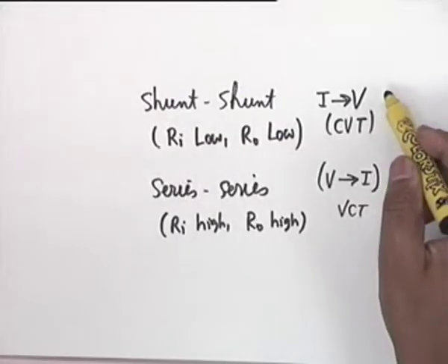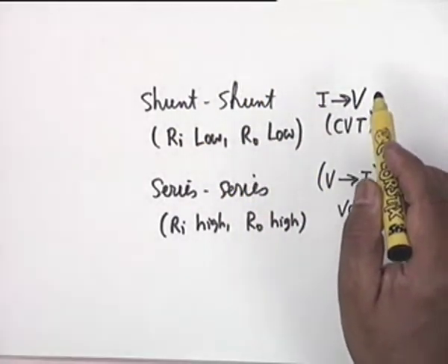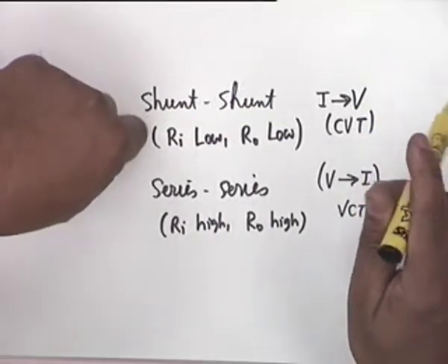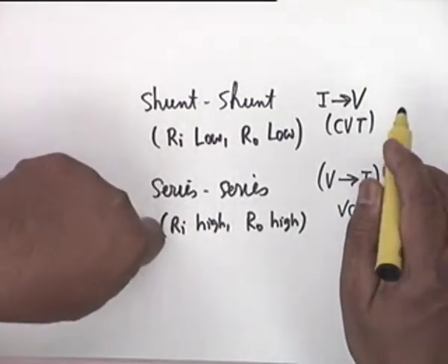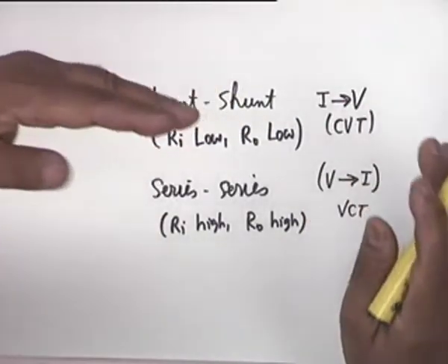But nevertheless, maybe you overdo this. That means if you want an FH of 1 megahertz, maybe you design this for 20 megahertz, and similarly, this one also for, let's say, 15 megahertz. Then you combine the two, you will surely get 1 megahertz. Okay, so you'll have to design. But in the process, you have reduced the gain. When you cascade the two, the gain shall increase.